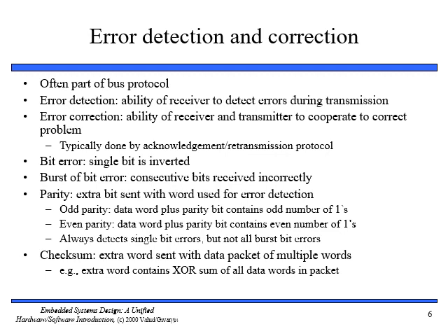Now we talk about checksum. Checksum is a strong form of error checking that is applied to a packet of data. A packet of data will contain multiple words of data. Using parity checking, we use one extra bit per word to help detect errors. Using checksum, we use an extra word per packet for the same purpose. For example, we may compute the XOR sum of all the words in the packet and send this value along with the data packet.